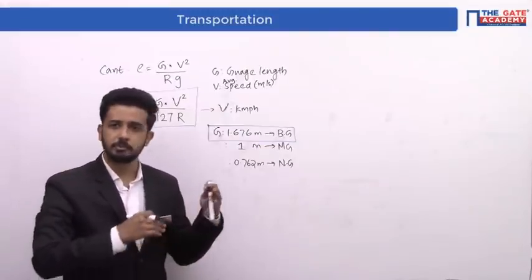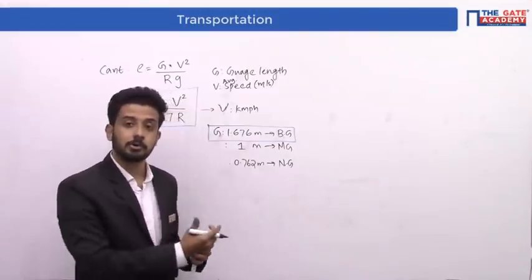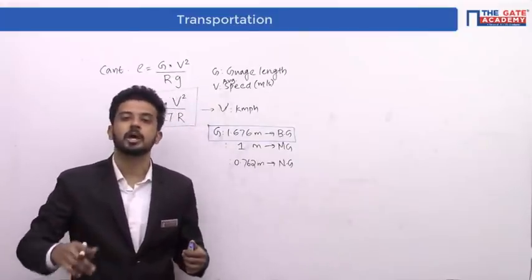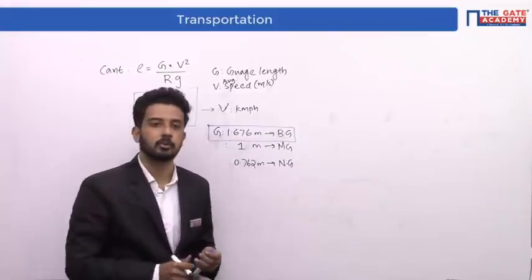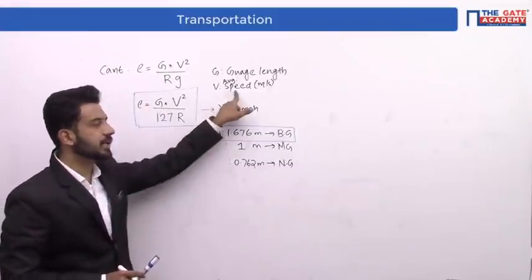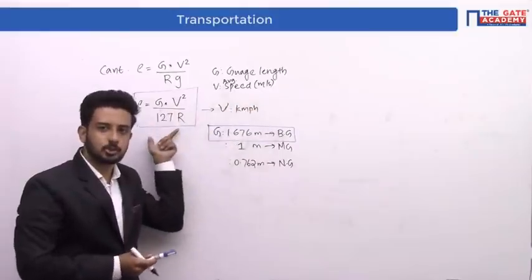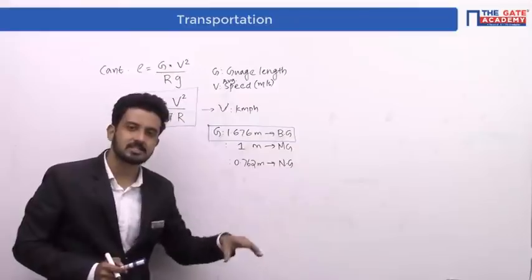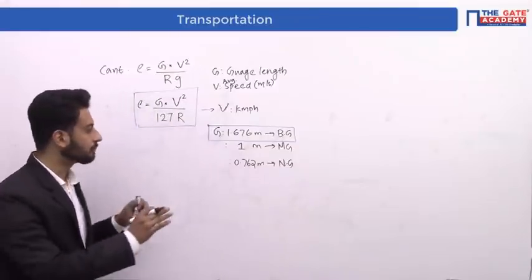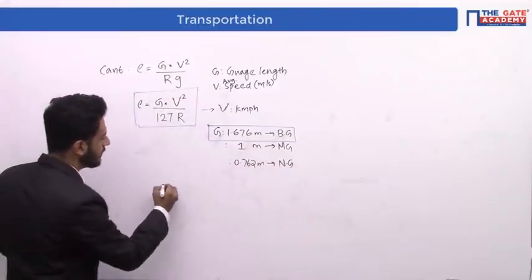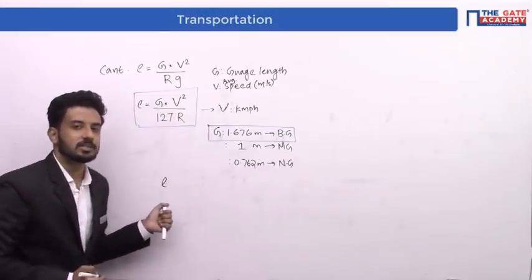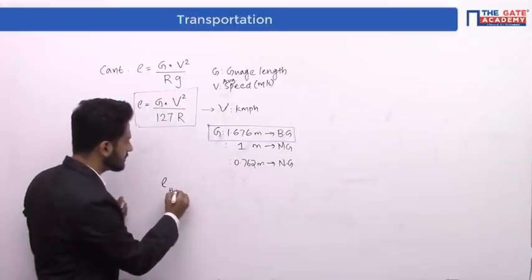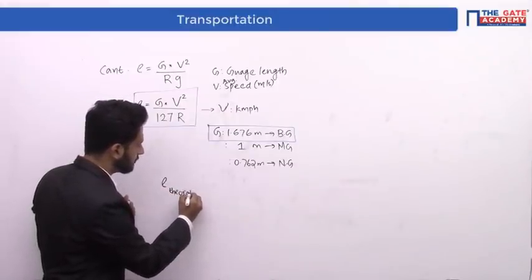So for the maximum speed, if they want to take, the super elevation should be somewhat higher, but we are not giving that higher super elevation because we are providing the actual super elevation based on average speed only, which is less than the maximum speed, correct? So the super elevation which is required for the maximum speed, I am calling it some theoretical value.